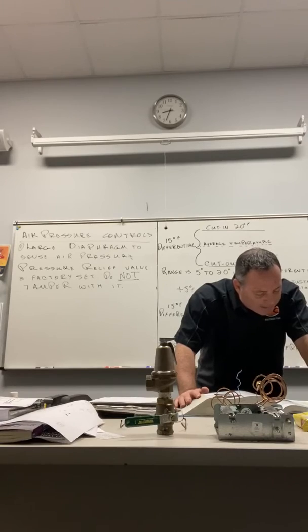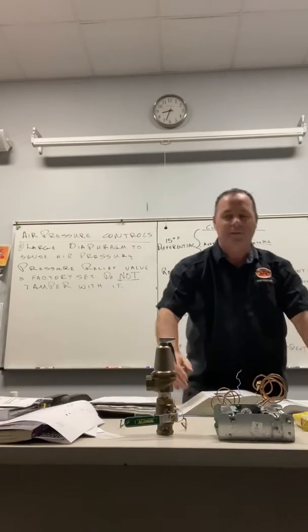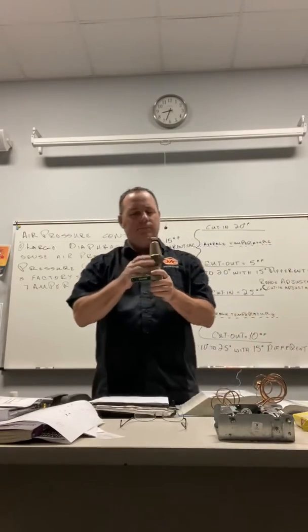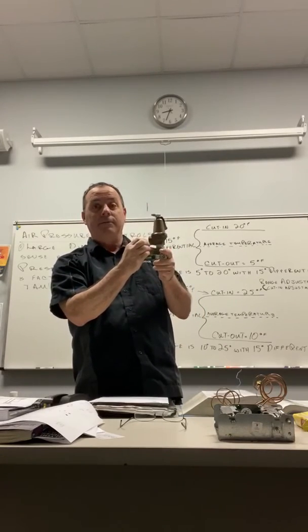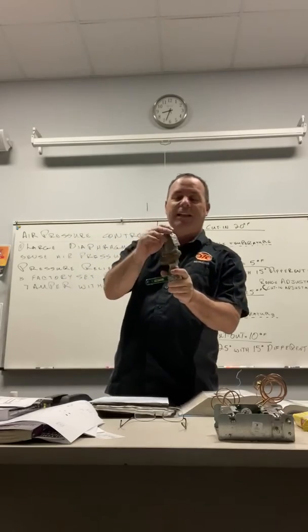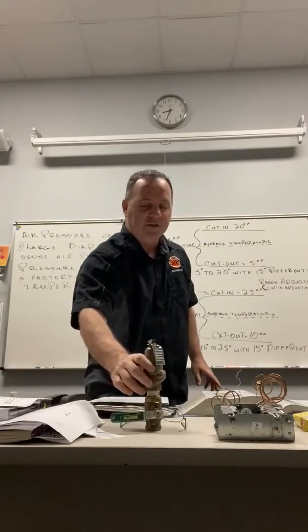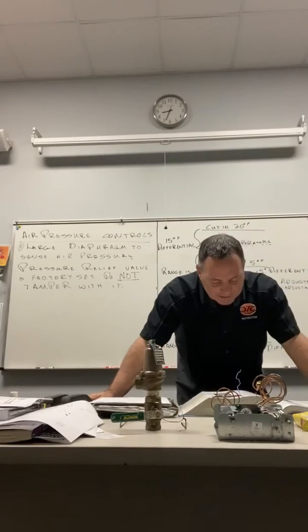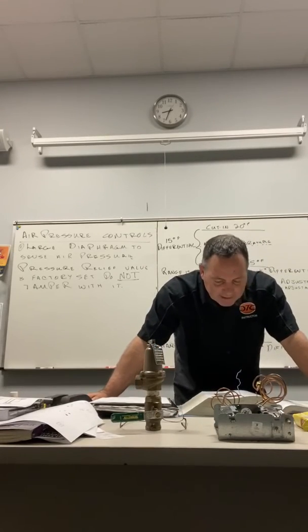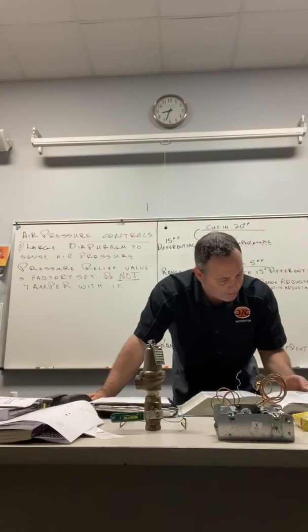A seeping, crying relief valve is bad. Change it. It shouldn't be leaking water out of it. If it is, get rid of the sucker. Water pressure regulators. We only got two things left in this chapter, so let's talk about that real quick.